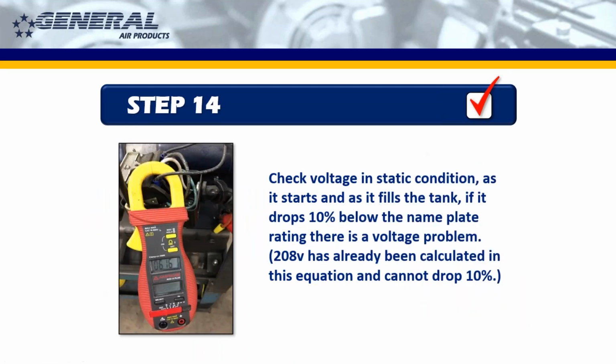While the unit's running, if the electrician is there, maybe you have your alarm guy with you, using a voltmeter to make sure that you're getting the right voltage to the unit is a great move. A very common issue is, let's say the main power panel is on one side of the warehouse, and a football field away is the air compressor. Somebody runs a 14 gauge wire across that building, across 300 yards, all the way to the air compressor.